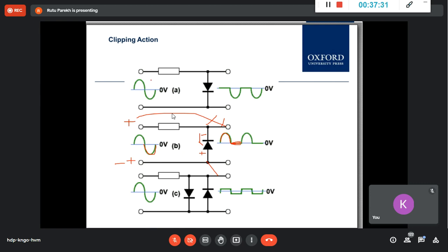So now this was an ideal diode, but in this whole universe, nothing is ideal. You can say everything is ideal also and nothing is ideal, so it depends on the definition. But practically, if you say this is ideal, then practical things are there, and practical means a 0.7 drop when it is conducting. So now you have to think if this is the circuit.